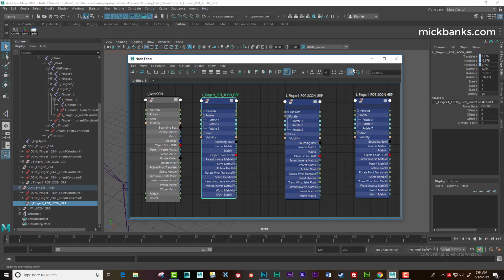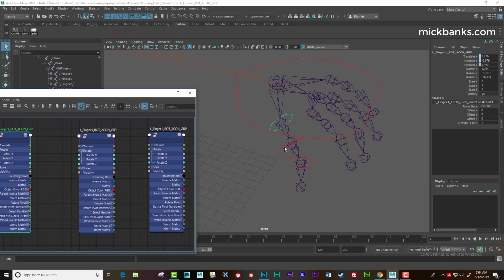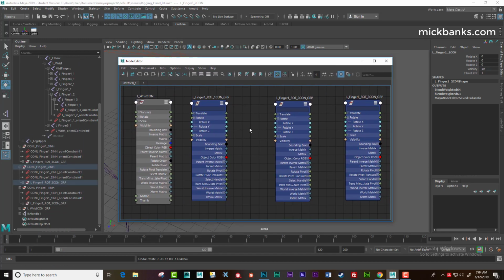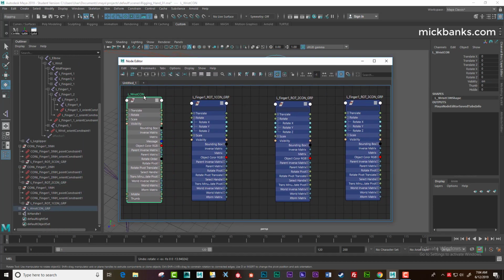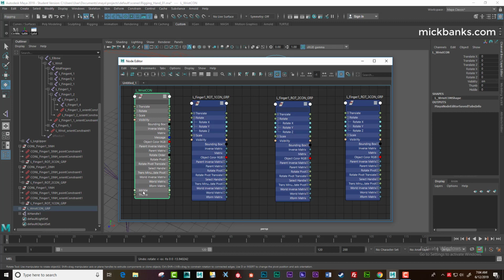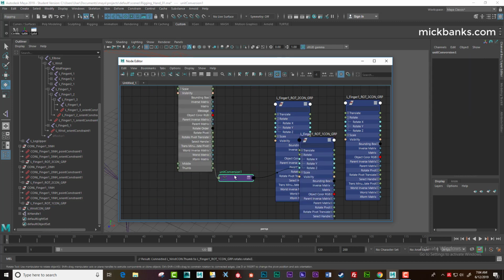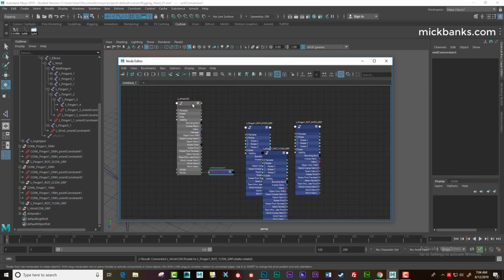notice the Z, and it should be the Z axis. We'll have a quick look, and we can see that by hitting rotate here, rotating one, you'll notice it's the Z rotational value. It's moving up in our channel box. See that? So that's the one we want to control. So here's the Z, and what we're interested in is our wrist control, the thumb, remember? So I'll grab the output of the thumb and drag that up into the rotate Z of this one, and it creates this little conversion. We're going to use that shortly.